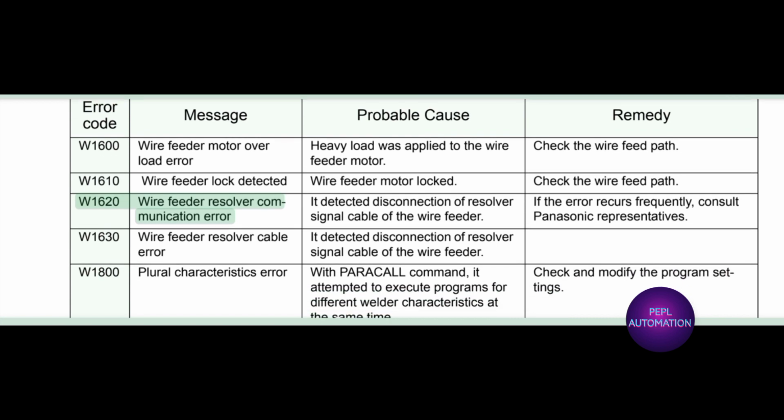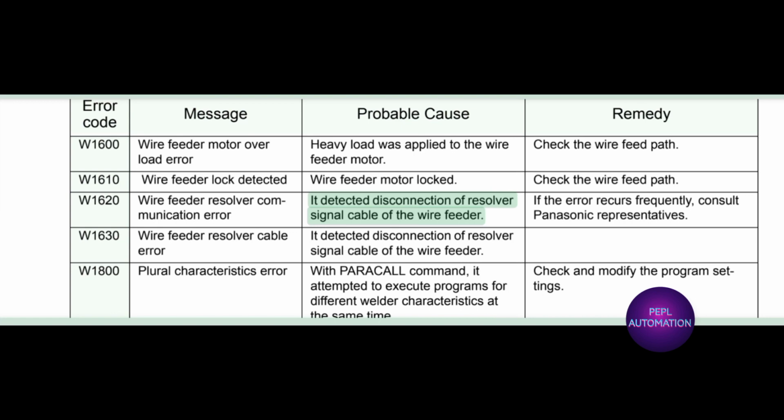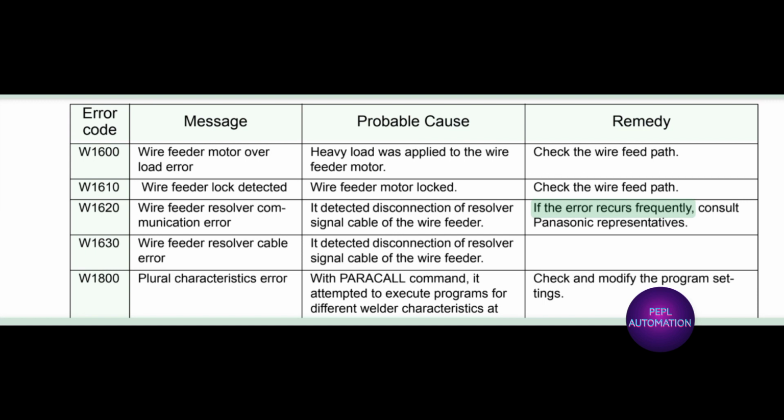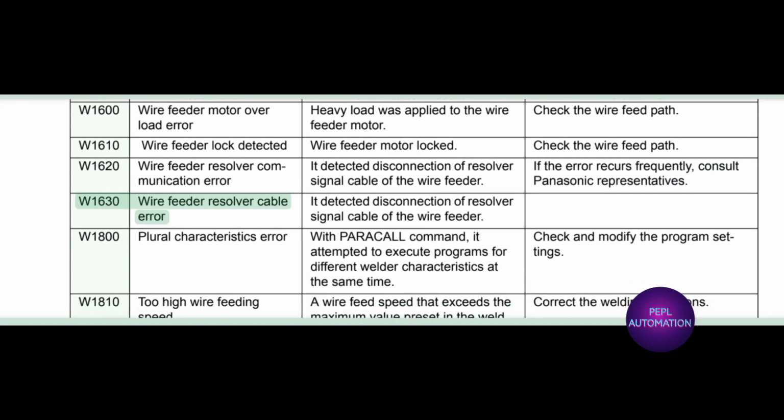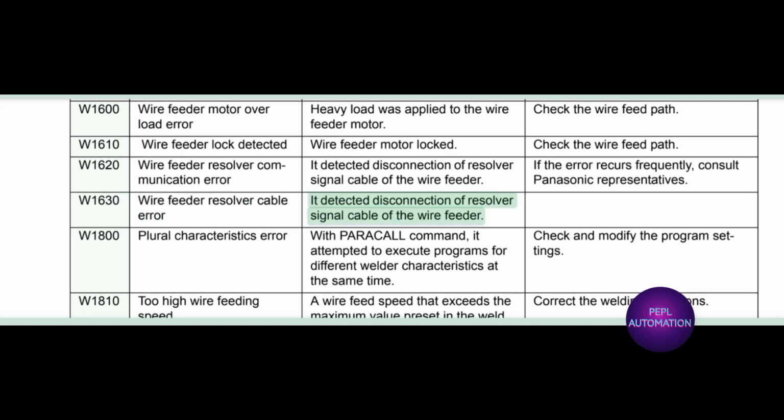W1620 wire feeder resolver communication error. It detected disconnection of resolver signal cable of the wire feeder. If the error occurs frequently, consult Panasonic representatives. W1630 wire feeder resolver cable error. It detected disconnection of resolver signal cable of the wire feeder.